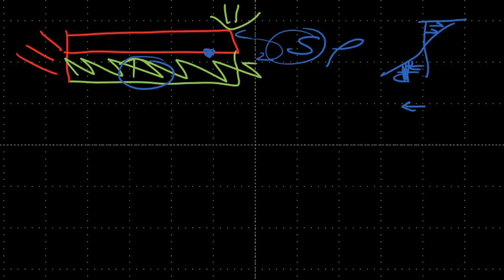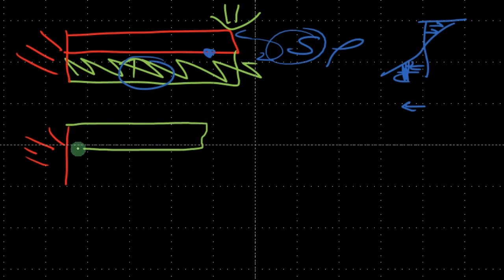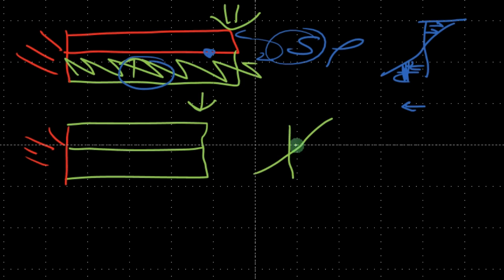The other case, if you want to do it the other way, you can apply a piezoelectric material in a bimorph configuration, in which case you can have a structure which is 100% made of piezoelectric material. In this case, if we apply a stress here again, we get tension and we get compression. But based on the way we orient these polarization directions, we'll get different results.